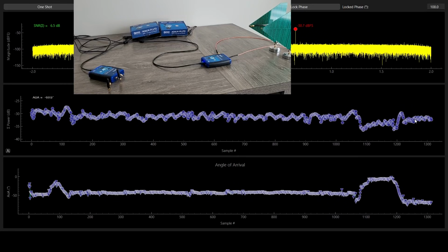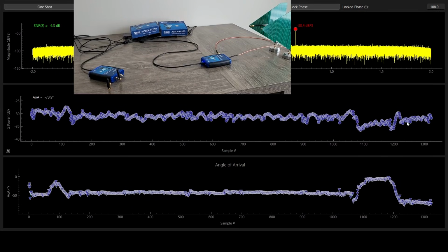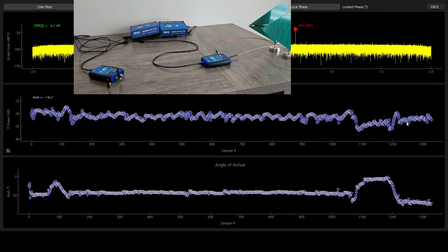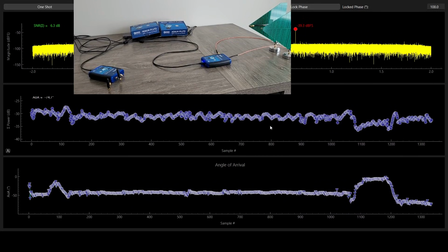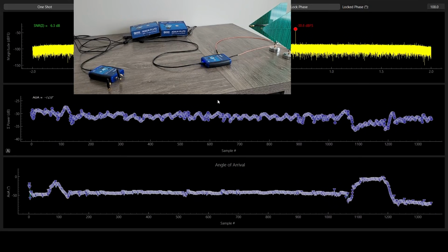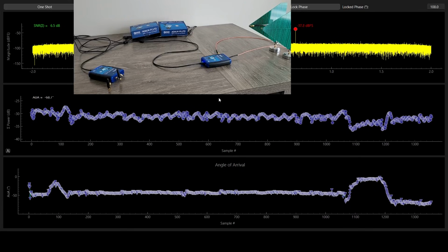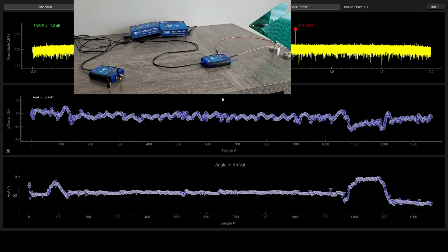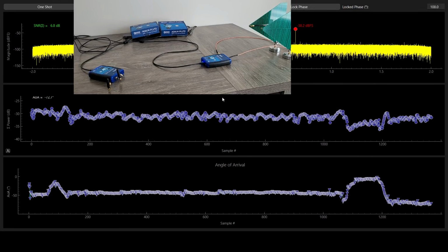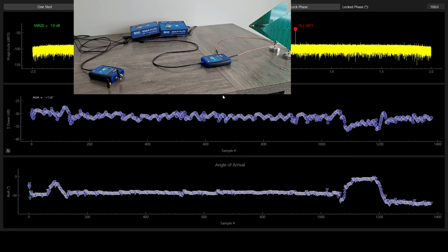This is because although it's an open loop behavior, we are not doing any feedback, for this second plot, as I showed in the code, we receive RX channel 0 and RX channel 1, and then measure the relative phase between them, and then add them together by canceling that phase.